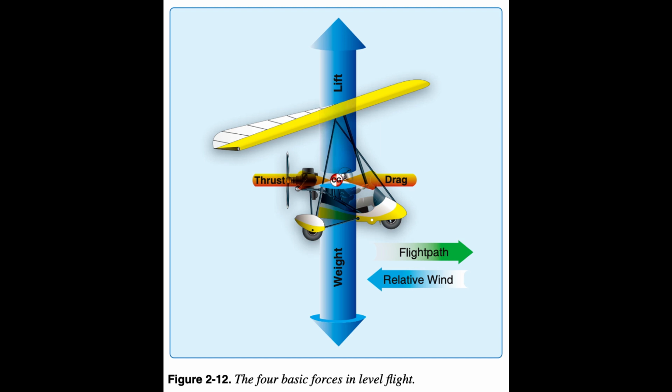Dynamic pressure, Q. Both lift and drag are a direct result of the dynamic pressure of the air. Dynamic pressure, Q, is created from the velocity of the air and the air density. An increase in velocity has a dramatic effect on dynamic pressure, Q, because it increases with the square of the velocity. Doubling the velocity means Q increases by 4 times.